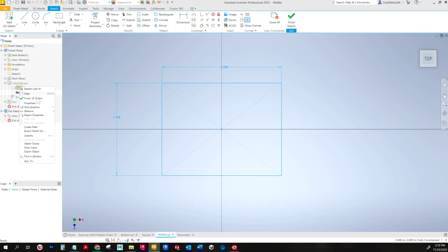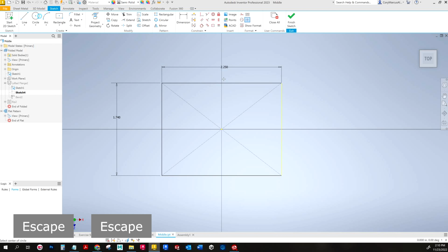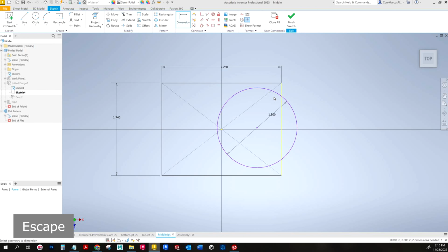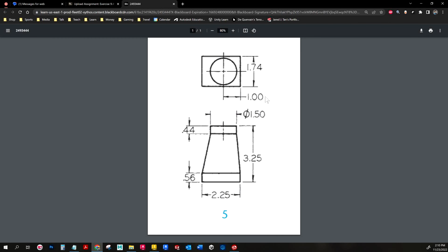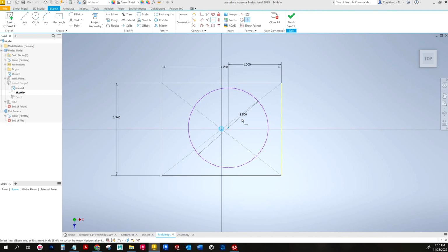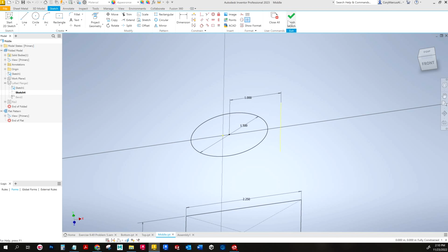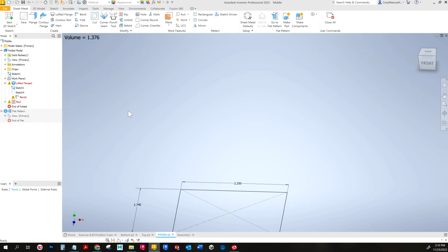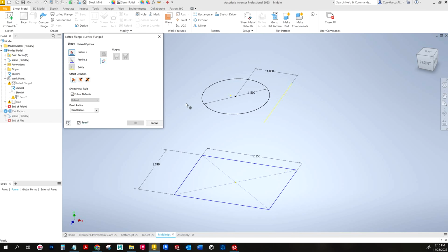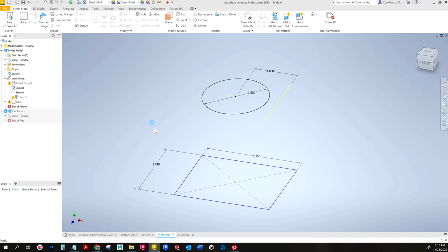So what I need to do for that middle part is turn the sketch on and project this edge here and draw a new circle. It's supposed to be 1 inch from this end, I believe. Let me double check. Yeah. So go back and fix that. All I did was basically delete the sketch and redraw it. You could actually unconstrain it, and if you did, it wouldn't do this if you just relocated it. But it's not that big of a deal to fix it.